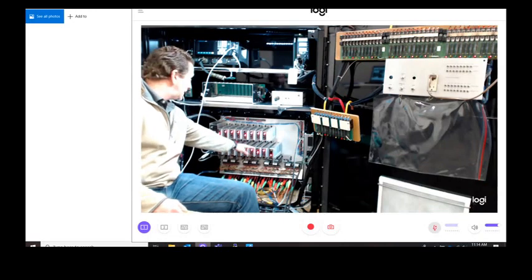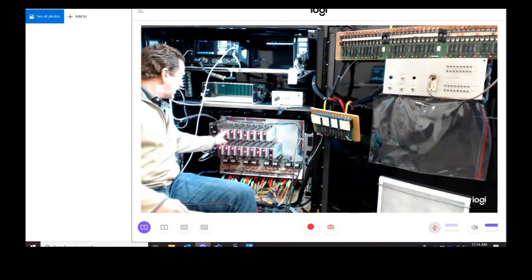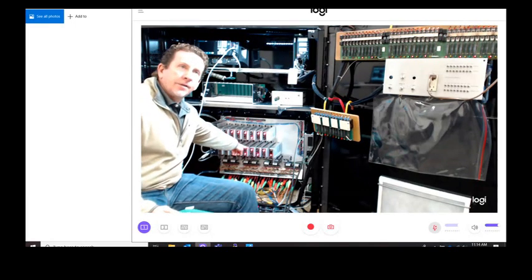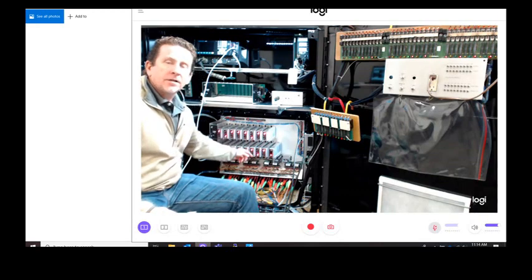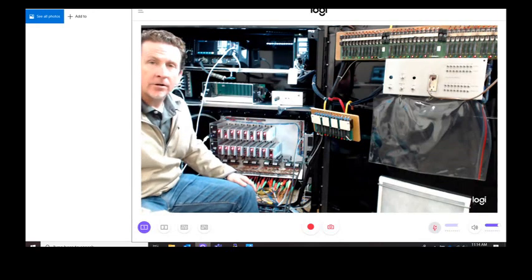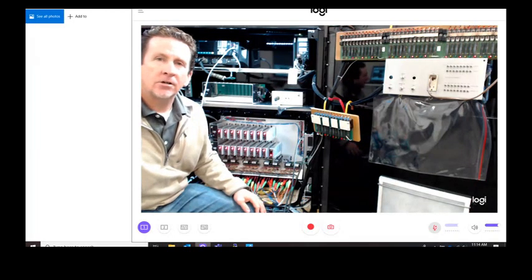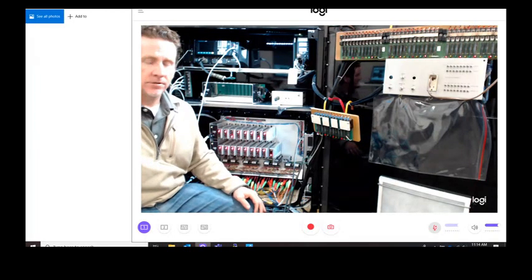So I got the green on 1, and then I got the yellow arrow and red arrow on, in this case, 13. Okay, so I have to do some programming in the monitor to create that combination of 2 load switches doing 1 signal.